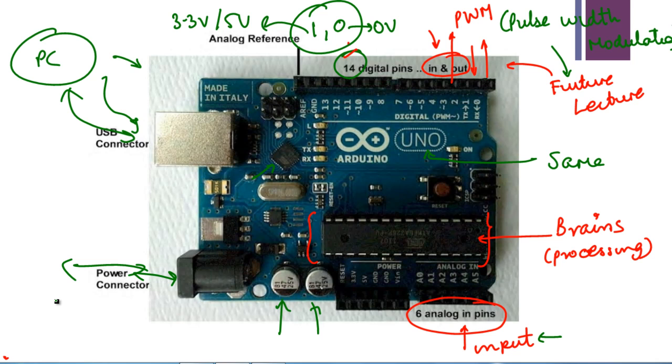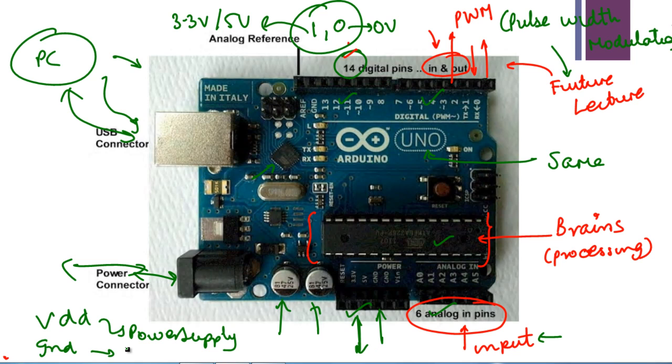So this was the Arduino board and understanding a few details of it. Just to summarize, the microcontroller, or the MCU, is the brains of the system. The I/O pins are like the hands and legs, as you can interface. You can also, for certain power supplies, take or give VDD or ground connections. Here, VDD is typically the power supply, so you can take that from the board. Ground, again, you can take that from the board.